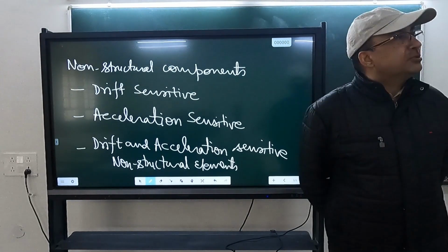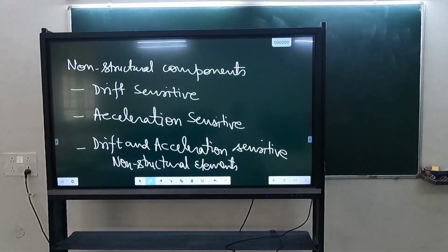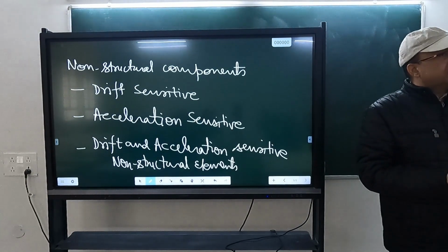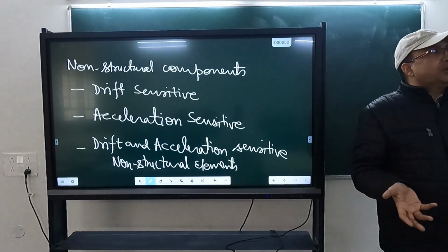Okay? But it is not a correct understanding. It is true if your structure is elastic. This understanding is okay if your structure remains elastic. So if you are comparing two elastic structures, then the structure which has been designed for a longer period will sustain less forces. But we never design our structures that way. So this is one myth, one misconception, that flexible structures work better. Okay? If you have to control interstory drift, you have to increase its stiffness.